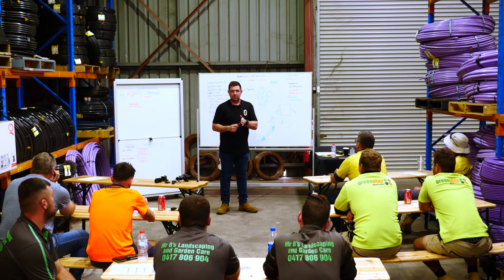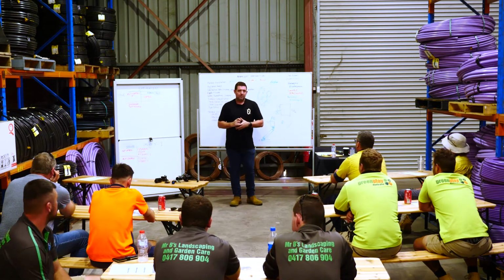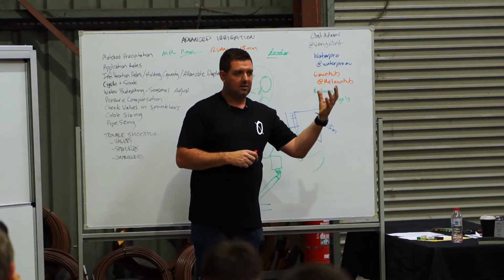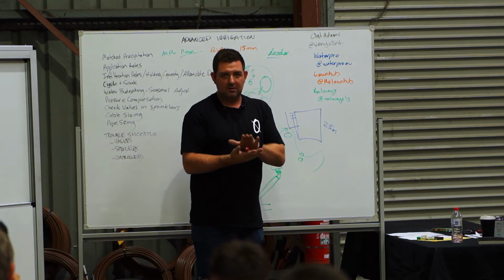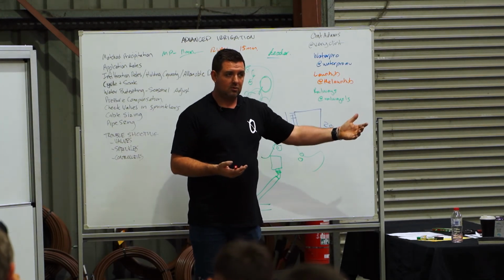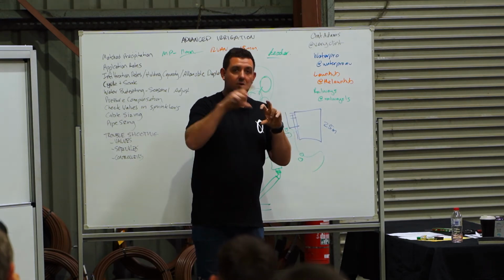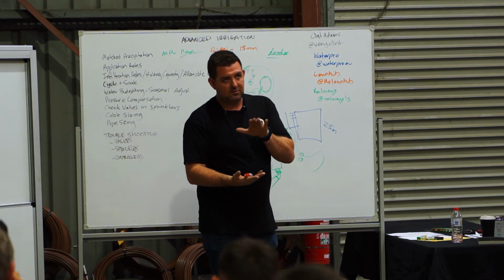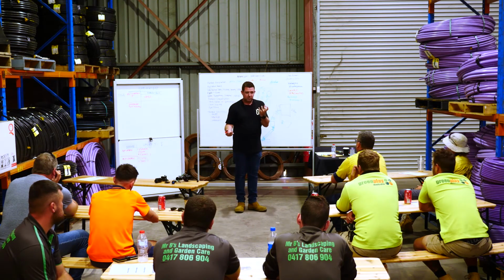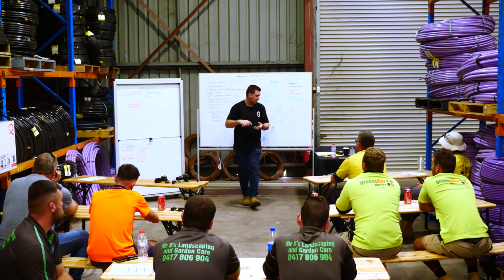a 1,000 kPa pressure rating. I think most of them now are pretty good. I know in the past we've had 690 kPa ones. If you're going to stick a 690 kPa pressure rated tap timer in a house, even with a 500 kPa pressure reducer, when that turns off, it's going to spike. You want to put a pressure reducer above the timer. The pressure reducers that we sell for after a solenoid valve are not rated for static and continuous pressure, so you need to buy a different pressure reducer because they will blow if they're under continuous pressure.